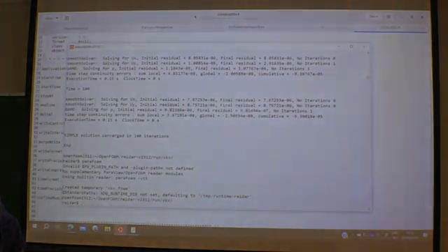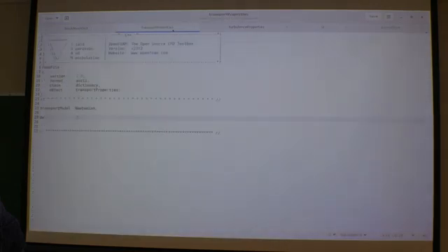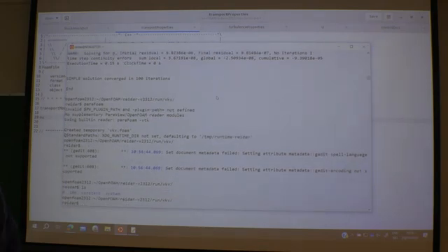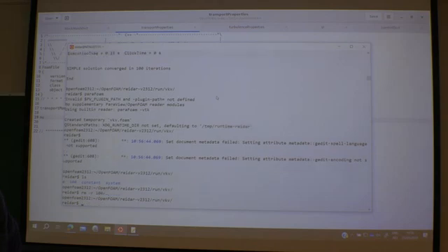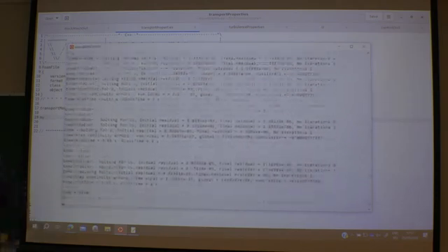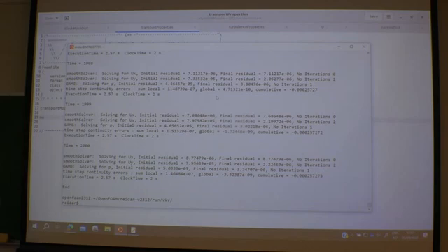Okay. Let's then change the Reynolds number. I will go to 100. Okay. Let's see, I only have one result folder, so let's remove that one. The 100 folder. So now I don't have any results, and I can simulate again. simpleFoam. He went all the way to 2000.